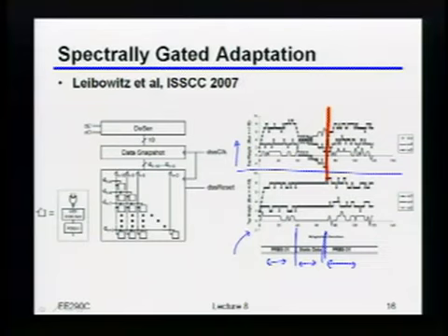The only bad news is that if you do something like that, it does put a little bit of extra burden on the receiver on the other side, because you have to find, OK, where in this scrambling sequence am I actually sitting? Did I start here? Did I start there? It's not too big of a deal, but that is a fairly powerful technique. There is still, let's say, like the dual loop convergence, where if you do the scrambling trick, then you really have to hope and pray that your real data is not correlated with the scrambling sequence. Practically speaking, that's usually OK. But there's no guarantee there. It's a great question. Yeah?